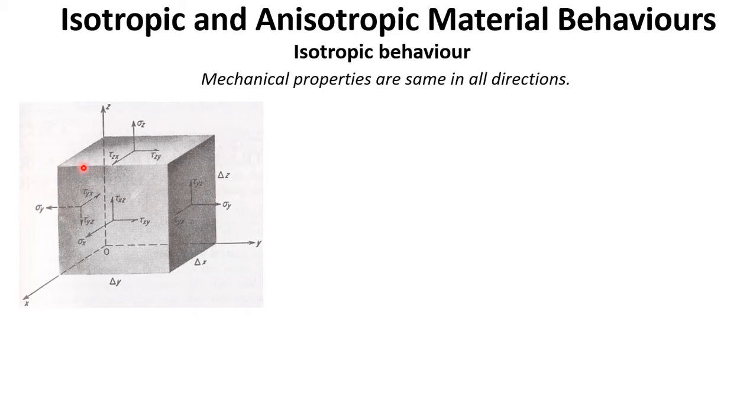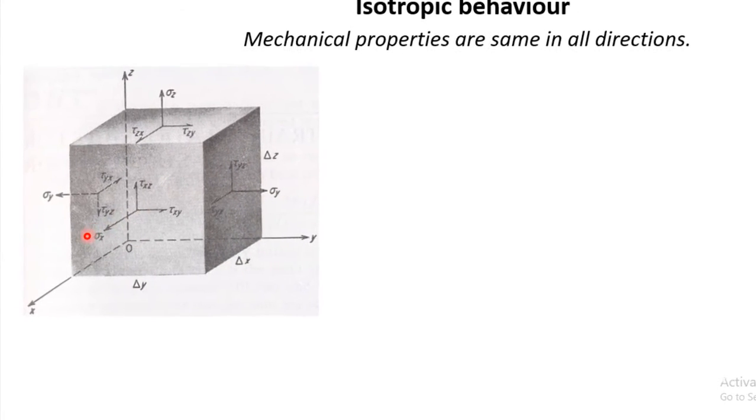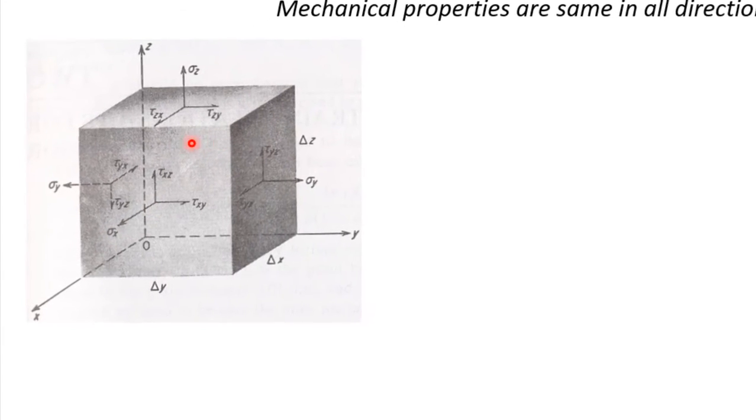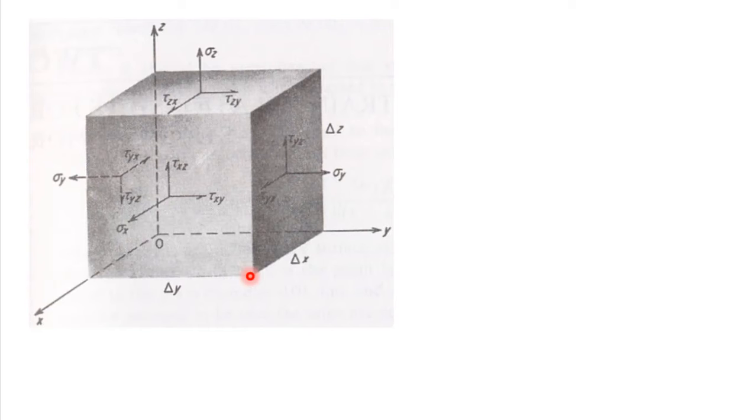And these are all the stresses which have been identified here. So for example, sigma x is in this direction, so it is acting on this plane zy and acting in the direction of x. Similarly, sigma y is acting in this direction and sigma z is acting in this direction. Other stresses are all shear stresses.